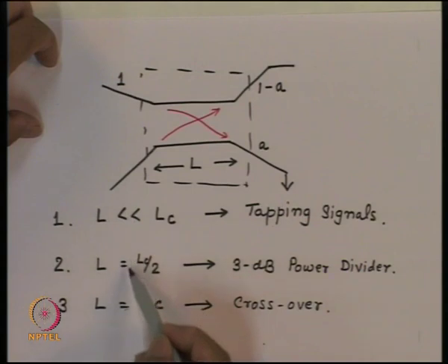If the refractive index changes, the coupling coefficient changes, and the coupling length would change. So, for a physical length given, if we apply the electric field to this, and if this device was made on an electro-optic material, then LC will change and consequently this relationship will change.